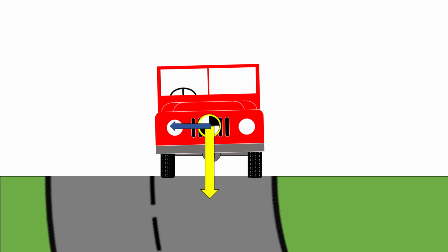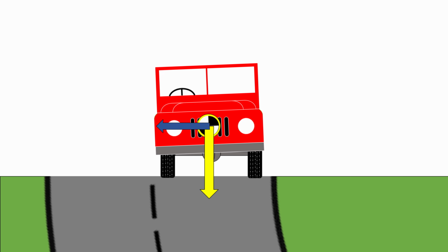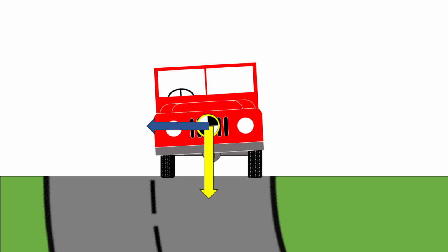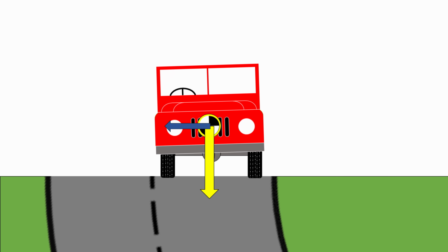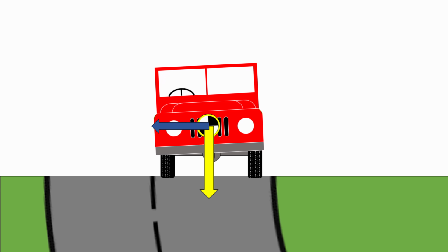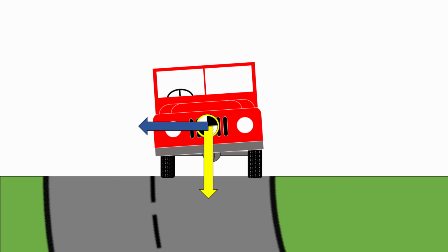And there is an equal and opposite force, which we call centrifugal force, which pushes the vehicle outwards towards the outside of the circle. That force, and in fact all forces that act on the mass of the vehicle, act through the centre of gravity. And you can see that as the vehicle speeds up, the amount of centrifugal force that's developing increases.